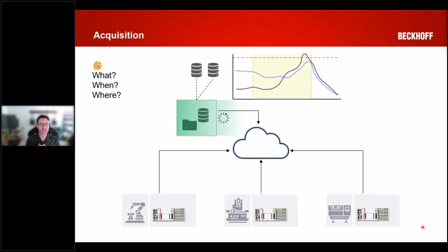And it kind of just brings everything together to make those crucial decisions, those what data is stored when and where. So if we revisit that same event scenario, some alarm occurs and we can take, for instance, the last 5 minutes of high resolution data from a short-term buffer and store it in a long-term database to analyze later.